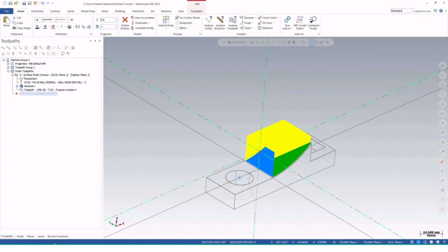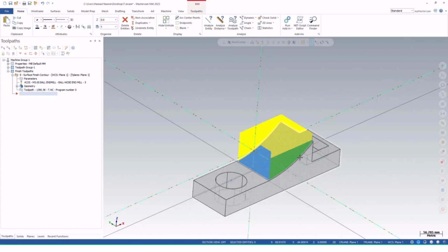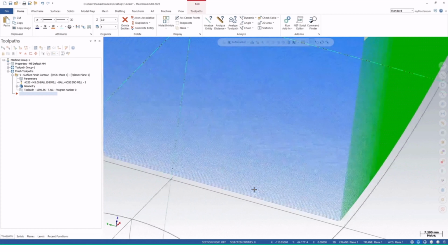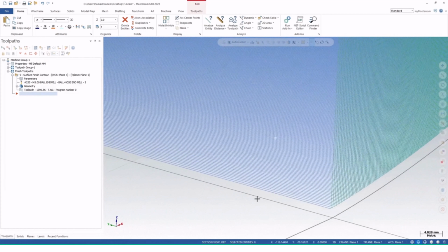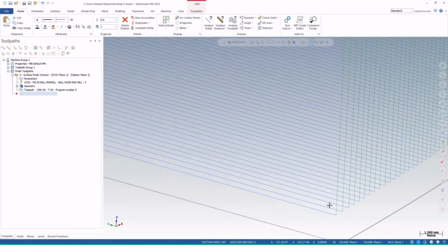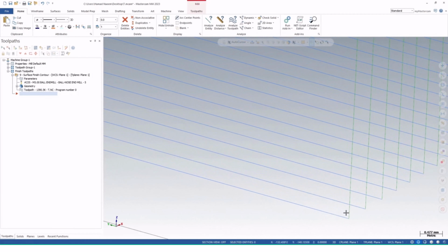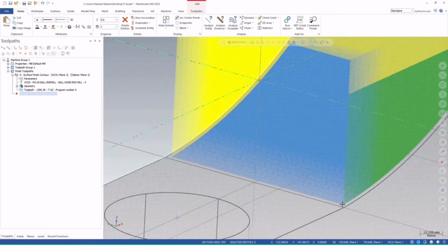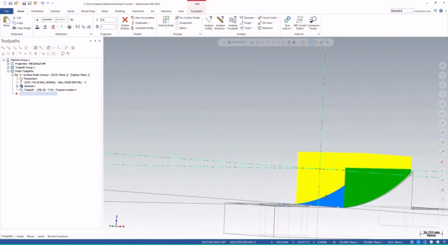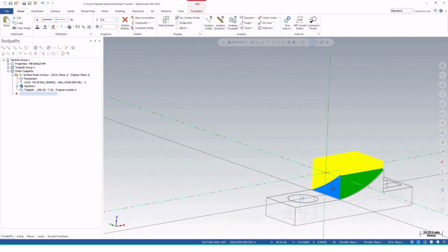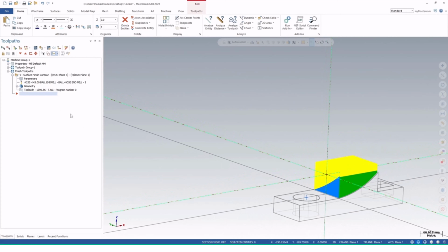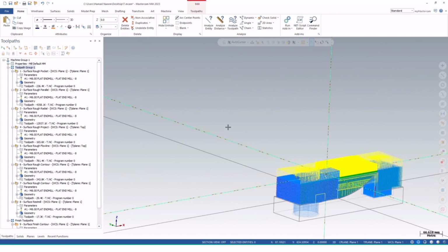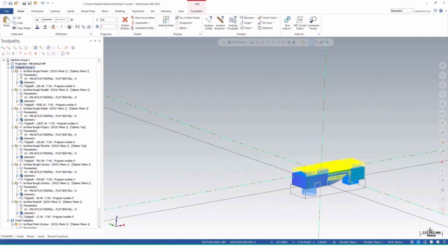And here we have, so what you see is that we have to perform the finishing operations. You see that this is a very close step over, which is 0.05 millimeter depth, and the step over will make this surface a very fine finish. Okay, so I hope you understand how we perform the finishing operation and how we perform the surface rough operations on a solid body.